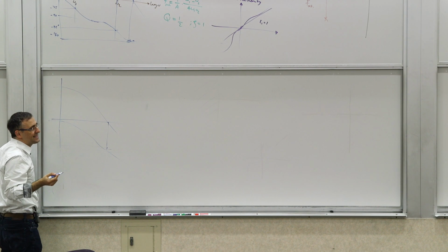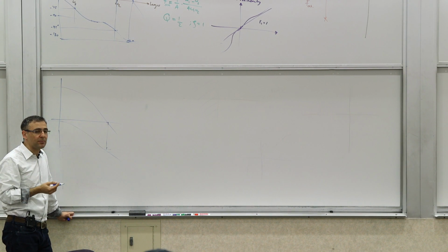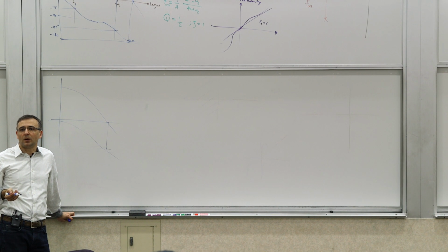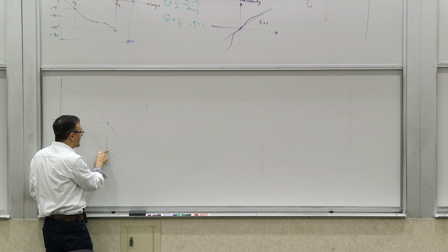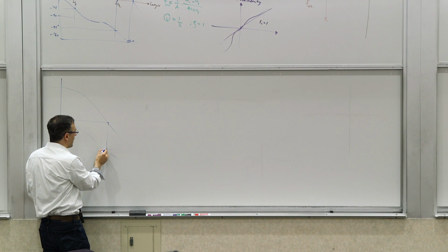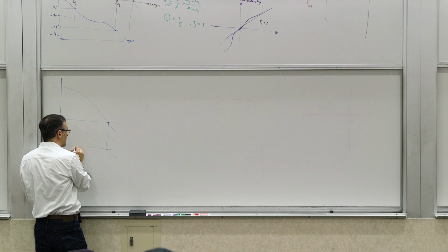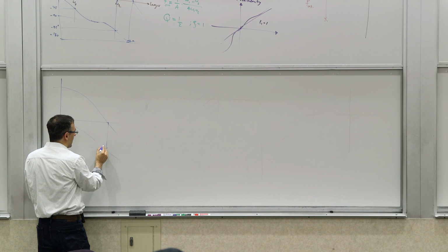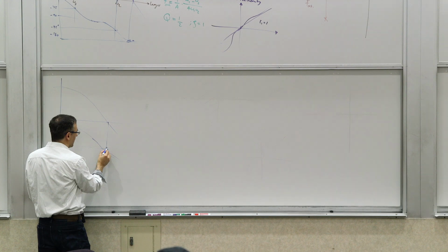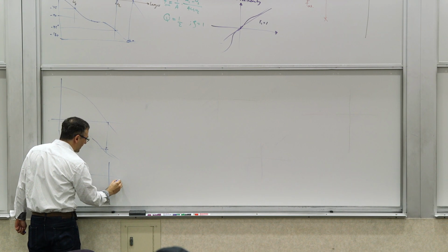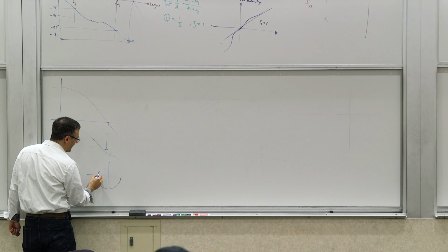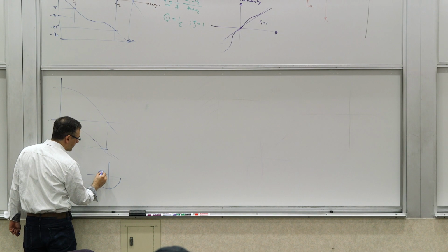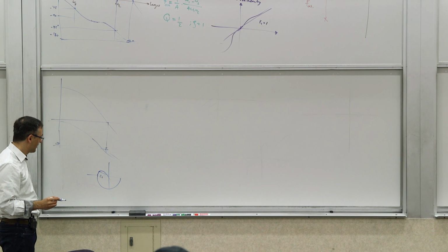That is another way of saying that, from a Nyquist perspective, at the point where you had unity gain, you had a phase beyond -180, which means you had encircled the point -1.